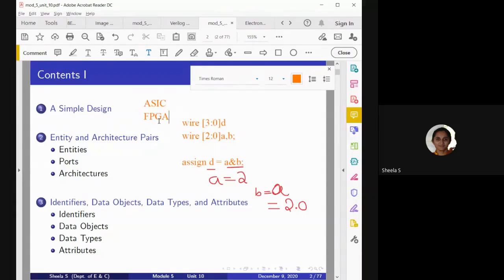Even after manufacturing, we can program and redesign the corresponding circuit required. As an example from Xilinx, when we consider the Spartan 6 IC, that IC operation can be programmed. We give input, do our own design, and place that design in the IC, and then we check, isn't it? It indicates that we are programming the IC.